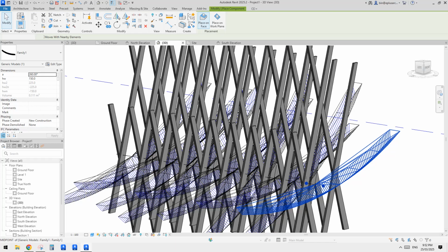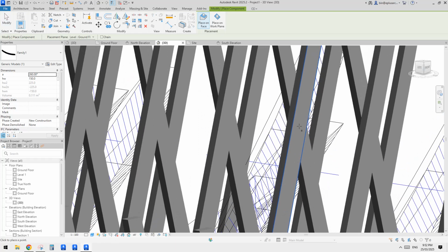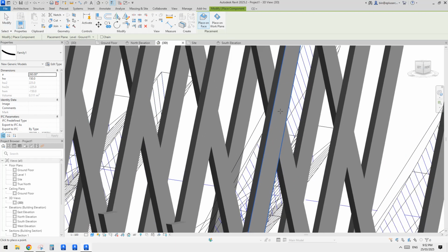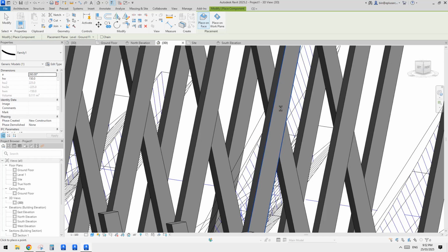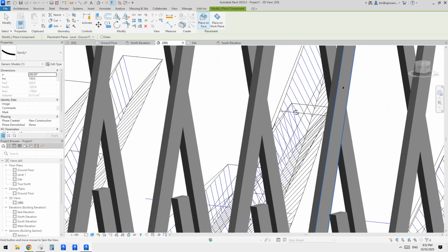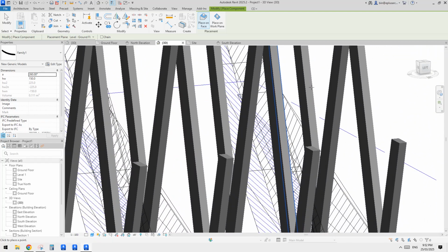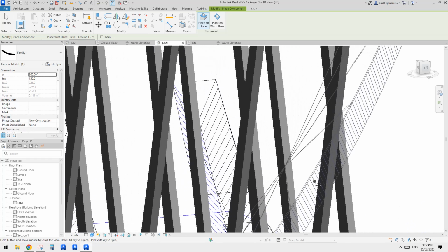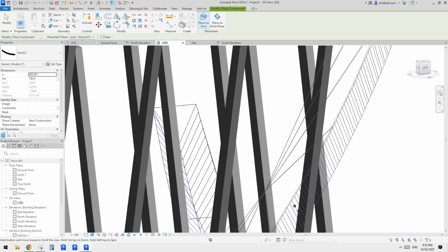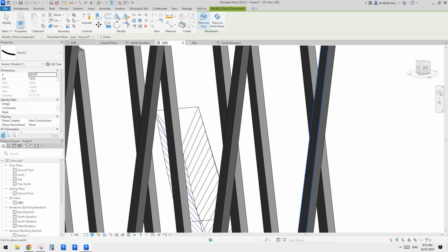So we're going to just click on, so roughly here. So I guess it's about here. So I'll just click once, and you just need to go rotate this view, and yeah, just be careful because Revit tries to create that family in place, so wherever you place this point now, we just need to pick that point.